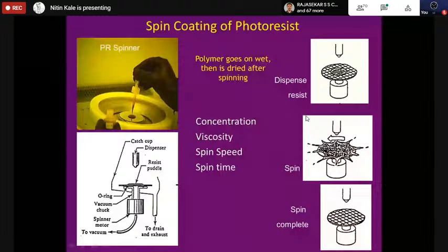Here it is important that the humidity of the chamber is controlled, because at very low humidities, the photoresist will tend to crack since solvents tend to escape from it.